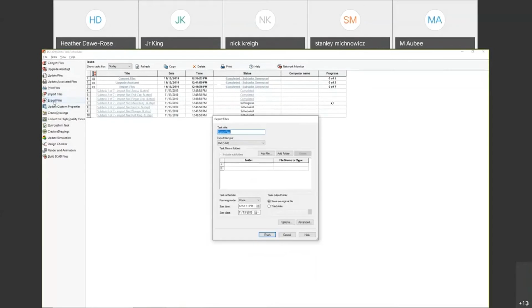And in the same way, I can do the reverse, and I can export files out to different file types, whether that be a step file or a parasolid. Just a note on which file types work the best with SOLIDWORKS. If you can, and whoever you're exporting it to can open these, I always suggest opening a parasolid file. They do work the best.